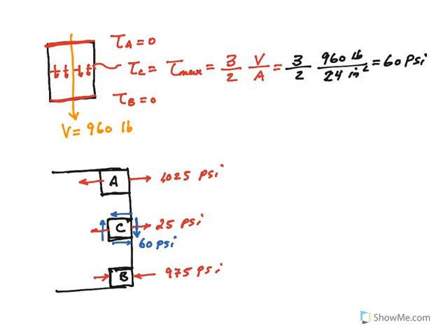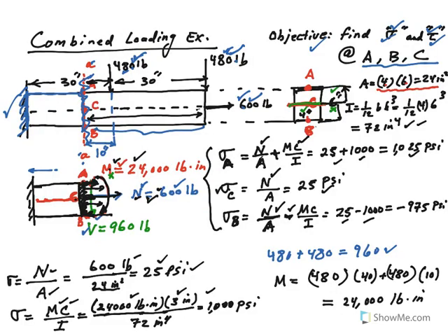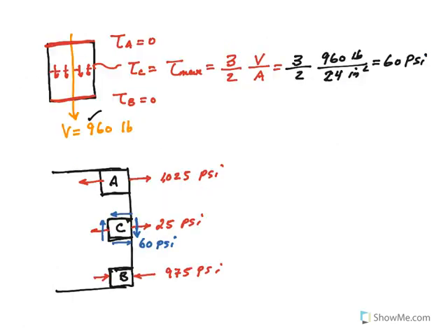Now you guys remember from the chapter with the transverse shear stress that we have a shear load that I calculated in the previous page. Here it is, 960. I'm redrawing it over here. Now you remember that the stress changes parabolically like that, and this is point A, so tau at A is 0. That's why I have tau at A 0 here, and tau at B is also 0, right? And tau at C, this is point C, becomes maximum, right?